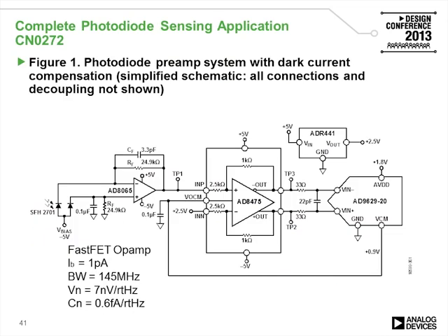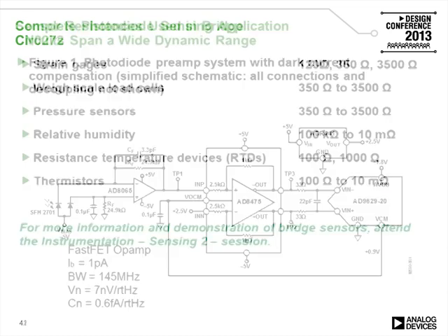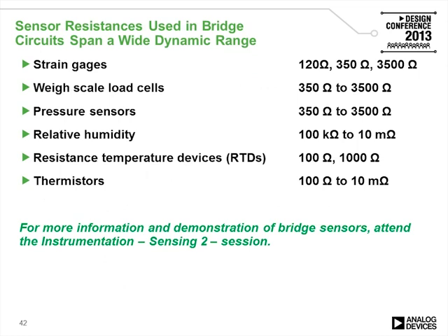This also can be built up into a more complete circuit, such as our circuit note 0272, which is used for a variety of applications, including colorimeters. There are also a wide range of sensors which are built from resistors built up into bridge circuits, which is 4 resistors in a diamond configuration, used for many applications.